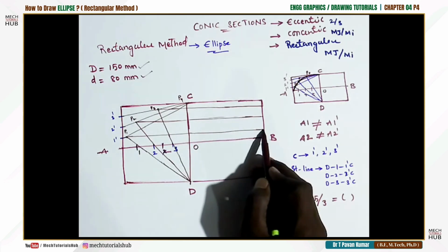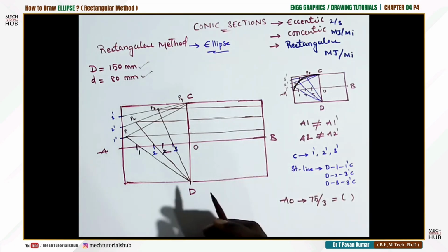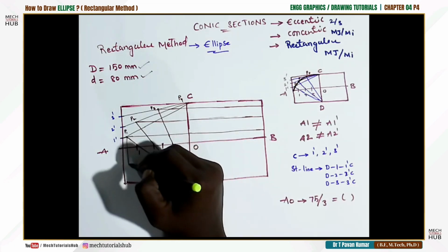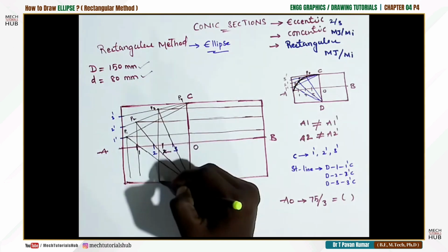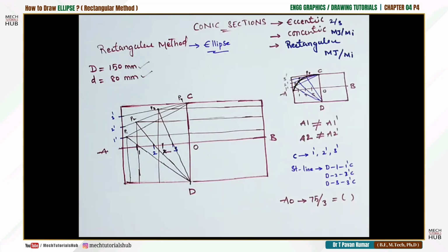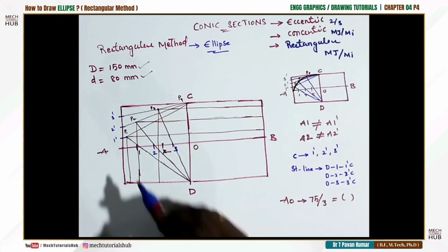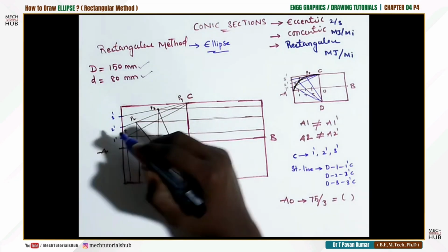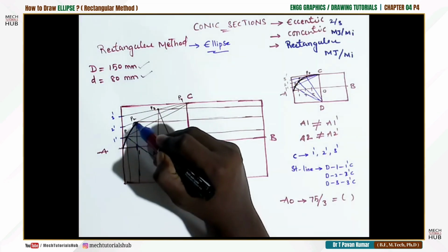But everything has to be drawn with a 2H pencil only. Similarly, I'll draw vertical locus lines also up to the horizontal. No need to erase the extensions later, not a problem. You can keep them the way they are. Now join A, P1, P2, P3 and P4 with an HB pencil, which is a dark pencil.